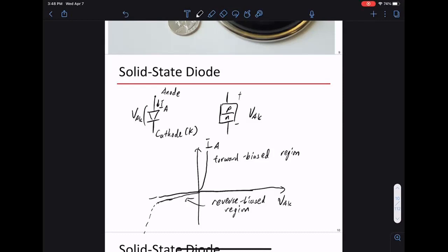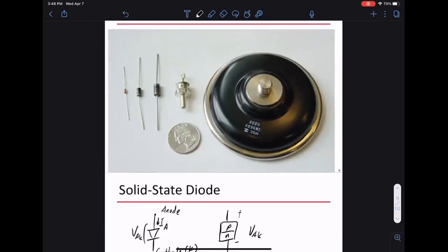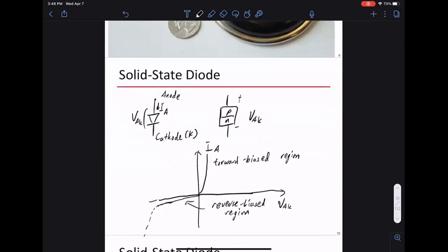Okay. So whenever we have a diode in the circuit, one thing in practical design you should always be careful about is that you don't break down the diode. Make sure your diode is sized large enough to not break down. Right? So that's why our diodes are this big. You don't want the diode to break down. For example, our voltages are in the kilovolt ranges, so you want to make sure your diode can survive that sort of voltage.